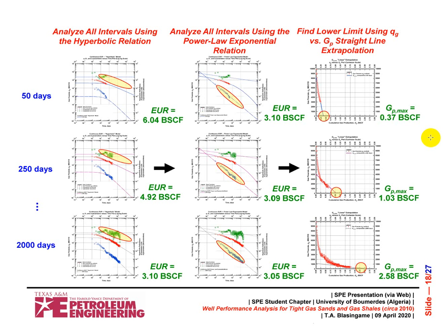That's why it's nice to have discussions with your colleagues. But the first extrapolation is extremely low. The next extrapolation is still low. But then once you're out here with a large volume of data, you can see that your extrapolation is very small, and your value should be reasonable. So again, progressing in time, 50 days, 6 BCF, 3 BCF, 0.3 BCF; 250 days, 5 BCF, 3 BCF, 1.3 BCF; 2,000 days, 3 BCF, 3 BCF, 2.6 BCF. So pretty good converging approach.